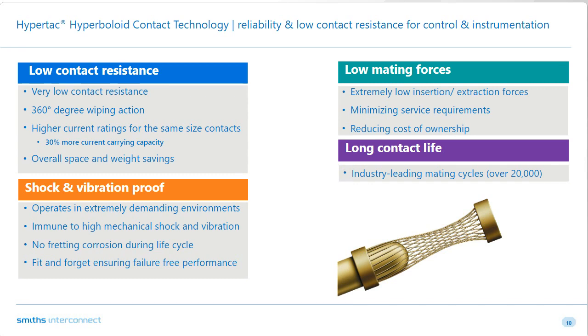The second thing that this contact technology does greatly is a 360-degree wiping action, which you see in the picture. Unlike any other contact technology that you typically see in the market, where you have various pins or various points around the male pin, here the male pin gets completely surrounded by the contact.